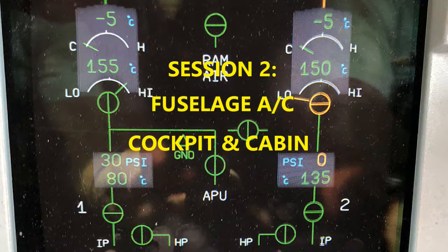And then you also have the water extractor. The water extractor is removing water from the hot bleed air. You also have condensers. The condensers are taking that cold air from the turbine of the air cycle machine. That decreases the temperature of the hot air from the reheater, to less than its dew point. So when that hot air temperature gets lower and lower, it's going to be lower than its dew point, and then you're going to have water in that hot air that's going to condense. So that needs to be extracted, and that's what the water extractor does. It removes that water from the condensers.